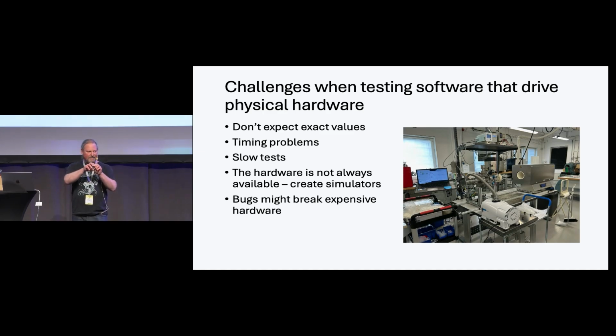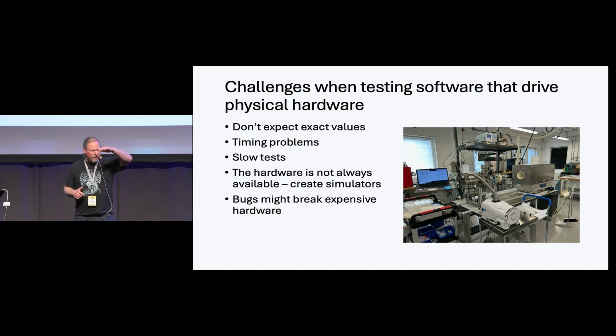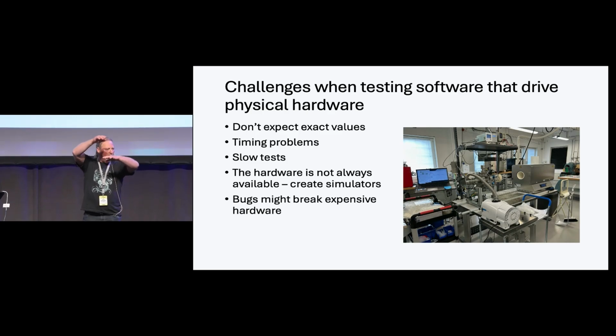So don't make exact comparisons. Always have a threshold or a range. The same thing when you switch on. You might need to have a threshold that, okay, I'll switch on when it goes above this level, but then you have a margin for when you're going to switch it off again, or your relays will click on and off, and burn out.